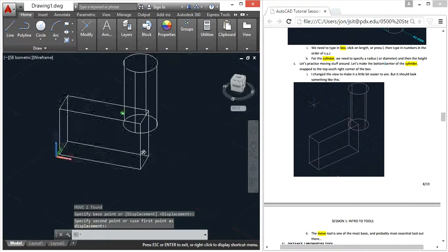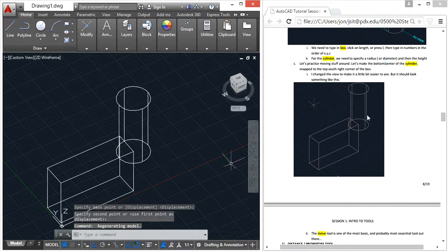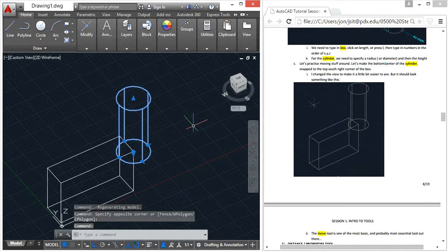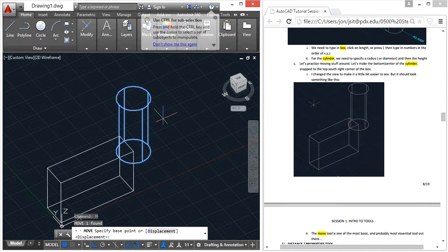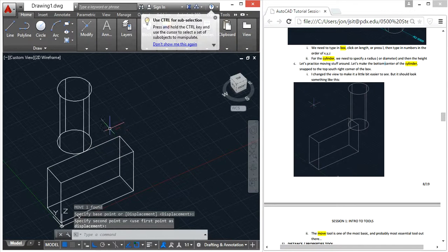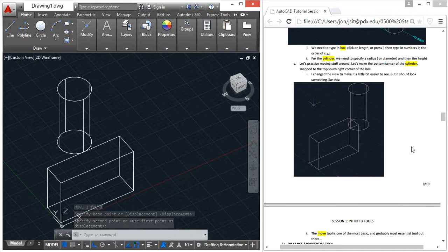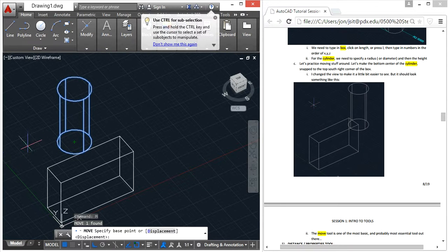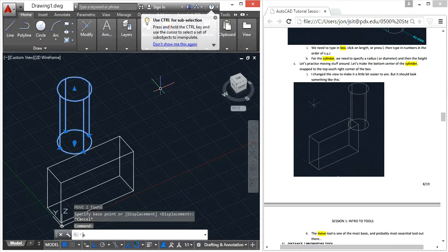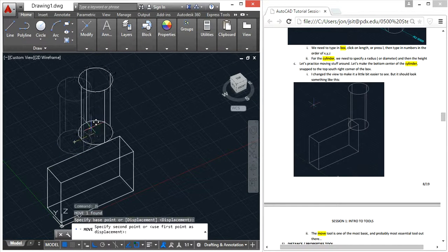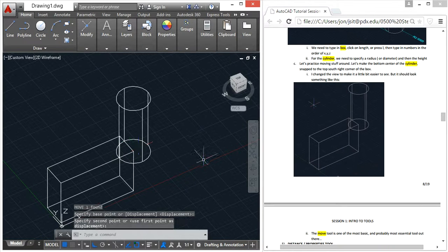Now it should look just like the PDF over there. Super essential, because what if I wanted it somewhere else? Let's say I wanted to move this, but using the quadrant snap over here to the midpoint snap. This is when the snaps come in super handy. So I'm going to move this back, right? So sometimes you might not have the center pop up. You have to go to the edge of the circle and then to the center. And then a little plus sign pops up.